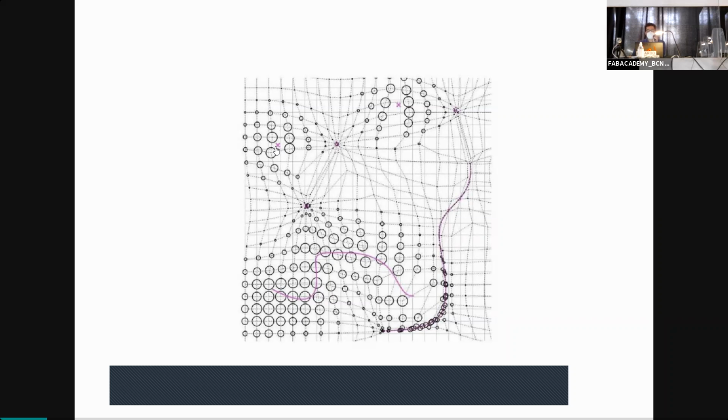When you have filled the array with circles, I will create 4 points manually that will be attractor points. Now I will measure the distance between this point and the ones close by. The closer a point is, the smaller the diameter of that circle. The farther the distance, the larger the diameter of the circle.